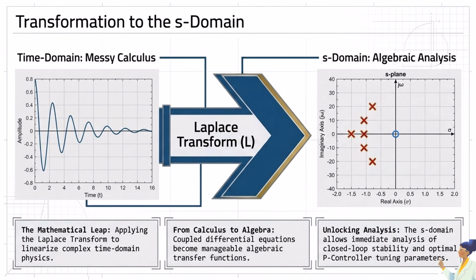Transformation to the S-domain. This is where the magic of control systems comes in: the Laplace transform. We take that messy calculus in the time domain and apply the Laplace transform to convert it into the S-domain. This transforms our differential equation into manageable algebraic equations. The mathematical leap is crucial.